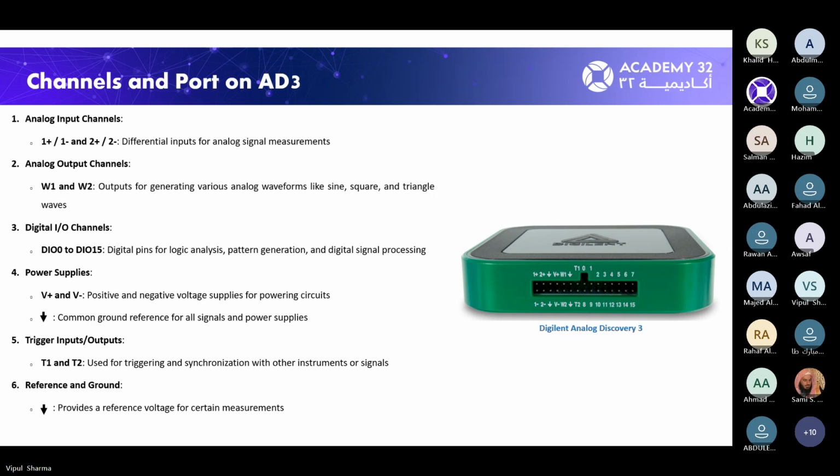So these ports will be used there. Then these are 1, 2, 3, 4, up to 15, these are the digital channels. If you are measuring some kind of a 16 channel digital signal, all of these can be applied here. Mind you, this is not a serial measurement, this is a parallel measurement. That can be measured through these channels.